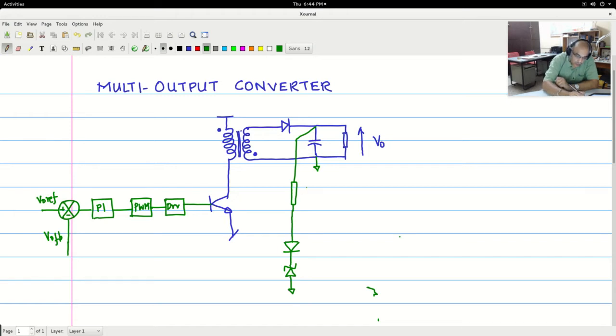So now if you look at the current that flows through I here, it will be equal to V0 minus Vz. You see, this is Vz, minus any diode drop, if you want to incorporate the diode drop, minus Vd. We say this is Vd, divided by R, and R is the impedance in this series path.